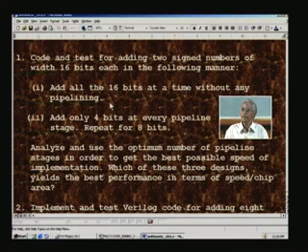Earlier we had done pipelining as far as the data bus width is concerned, by taking the LSB, and then pipelining functionality as well. Here I want it done without any pipelining: just add straight away and merely register it if you wish, and find out how much delay it can give. This is only for 2 numbers here. If you wish, you can do the same thing for 8 numbers and compare the results with the adder that we have already done. Another way is 16 bits at a time.